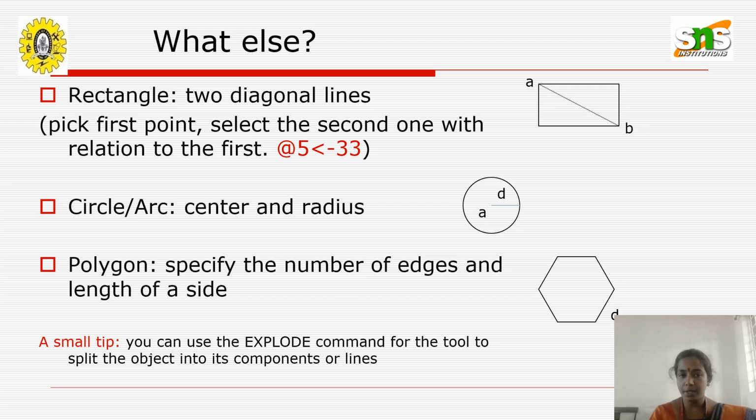You can also draw a rectangle directly in AutoCAD. The main difference is that a rectangle also has 4 lines. You can draw a rectangle using lines, from one point to another point, from bottom to top, top to left, and left to bottom. But you have to select all the individual 4 lines and connect them using the command called join.